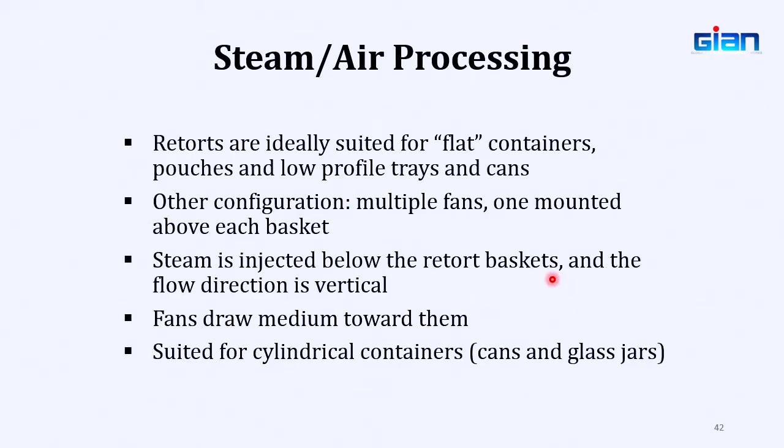So these kinds of retorts are ideally suited to flat containers, because as you can see the containers are lying horizontally and the heating media is flowing from one end to the other, front to back or back to front, in a horizontal direction. So if you have containers which are horizontal, then this heating media is parallel to the heat transfer surface.